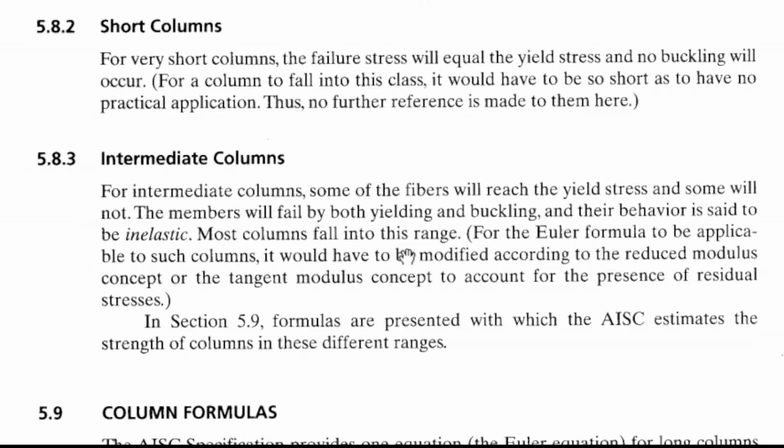15 feet is a long column, but it is within the Euler formula. But for intermediate, without modifying, usually it does not belong to the Euler, so we have to modify it according to the reduced modulus concept or the tangent modulus concept to account for the presence of residual stresses.